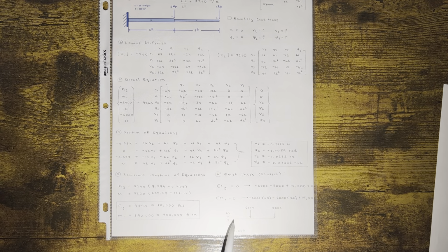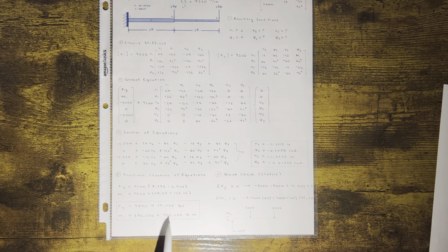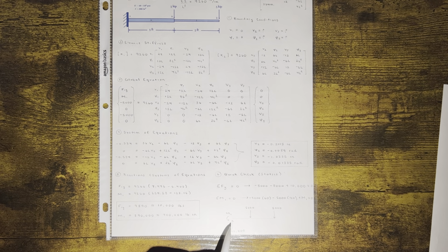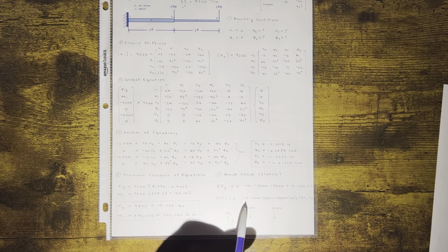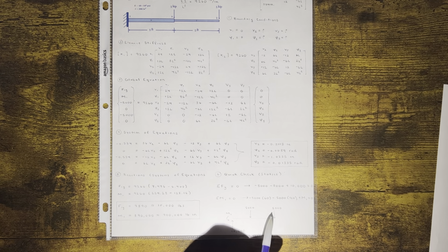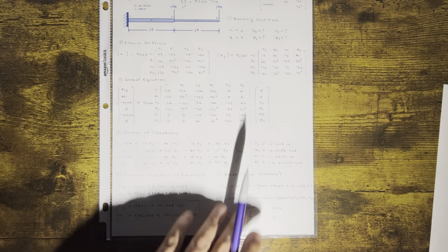So this is our beam in question. You have 5,000 pounds going down at node 2, and at node 3, 10,000 going up at node 1, 0 moment, and then you have a moment reaction of 900,000. So let's draw the shear. You start from this side and you work this way. In this case, you get bumped up 10,000. Nothing happens until 5,000 brings you down. Nothing happens again.